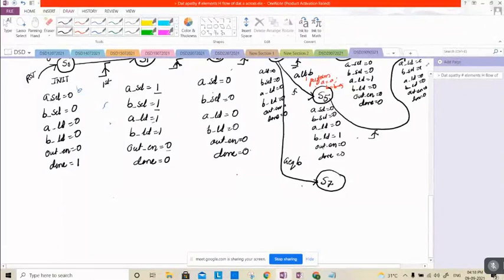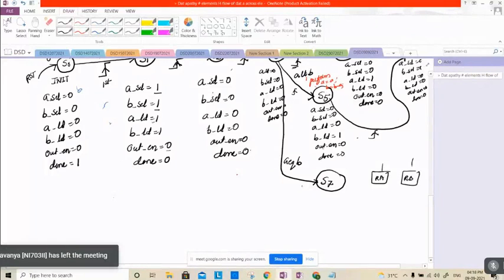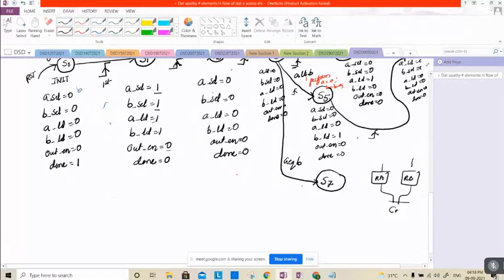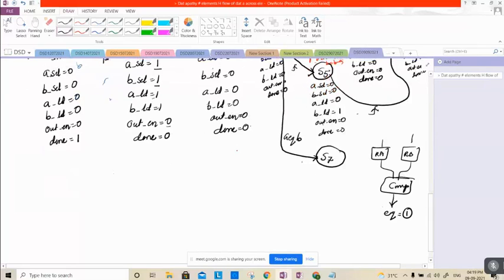We have said that A is equal to B. Whenever we have said that A is equal to B, what should happen? See, this is register A, and this is register B. From register A and register B, we are giving it to the comparator. So one of the comparator outputs is equality. Now equality says that this is equal to 1. So here another register is placed, called R out.